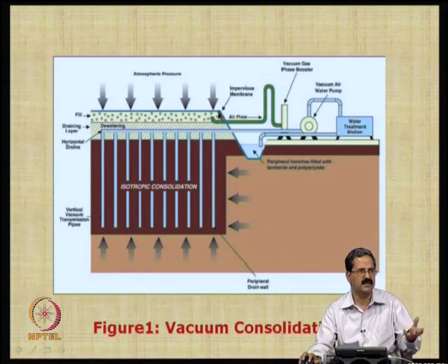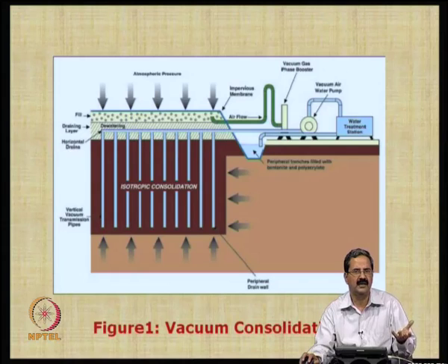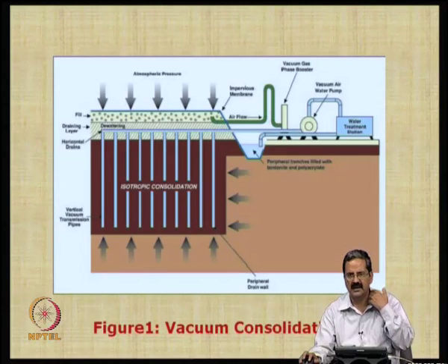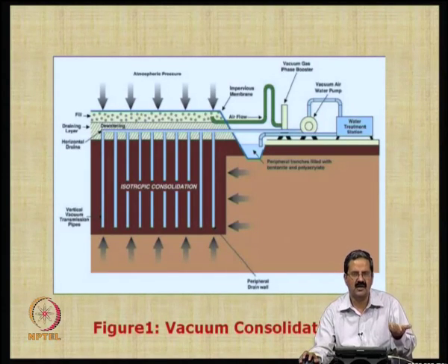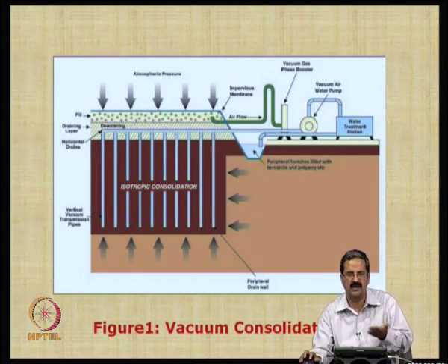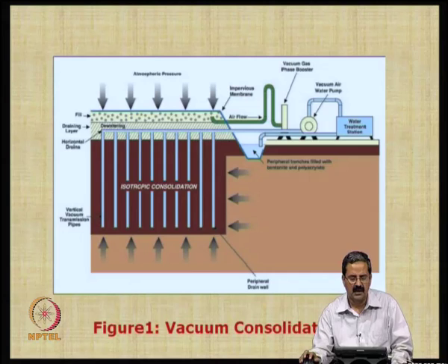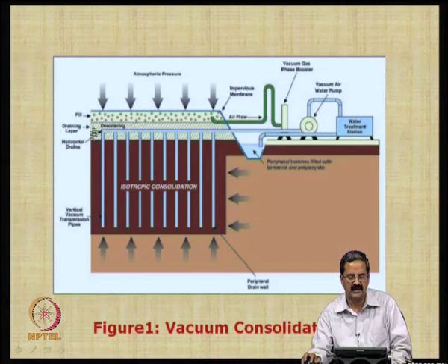Increase the effective stress means, if you put air, like we know that if there is air in the soil system, effective stress increases. Earlier it is only the pore pressure in a saturated soil, but if I have air pressure, which is called suction or negative pressure, the effective stress increases. It will be much stronger, similar to a saturated soil versus an unsaturated soil. Unsaturated soil will be much stronger and less compressible.